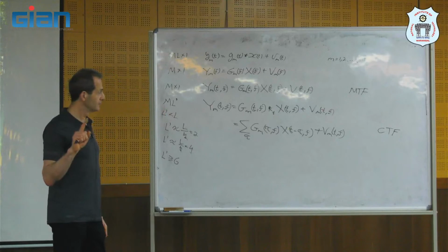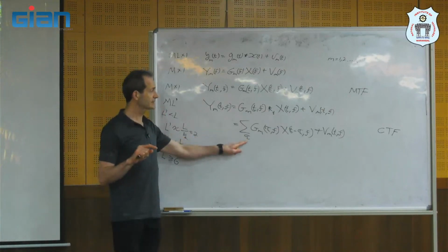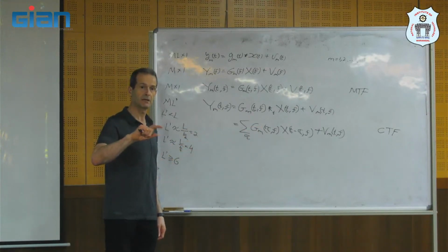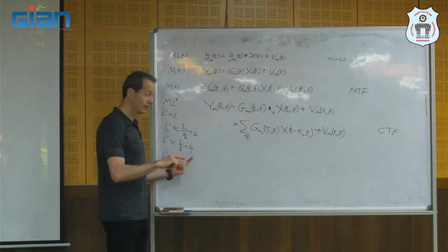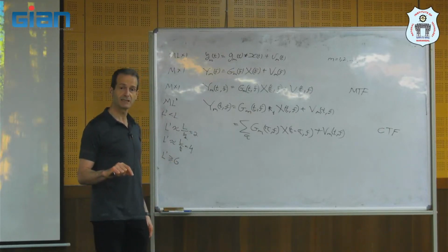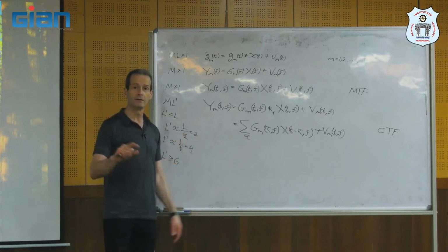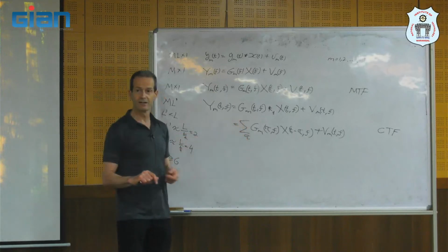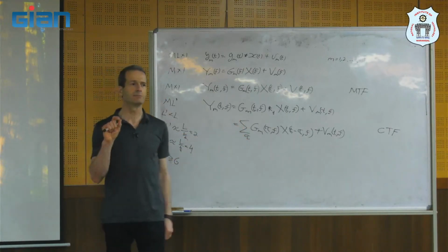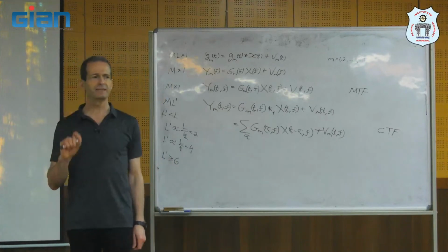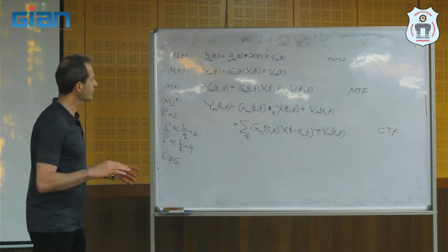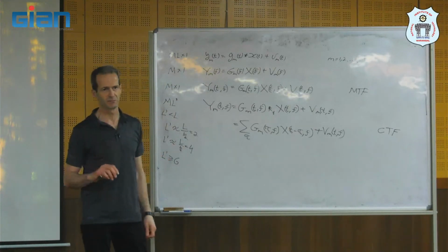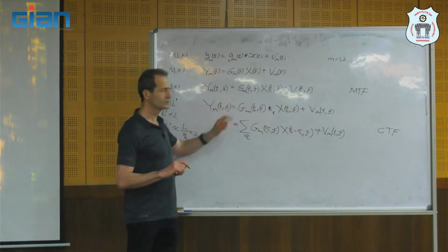And also, you see here, tau doesn't start from 0. It can start from -1, -2, depending on the overlap. So with 75% overlap, sometimes we start with tau -2. So it can be from -2 to 4. So pay attention to these important details when you implement or work with a problem in the STFT domain. This is very, very important, how you choose, how you define the problem.